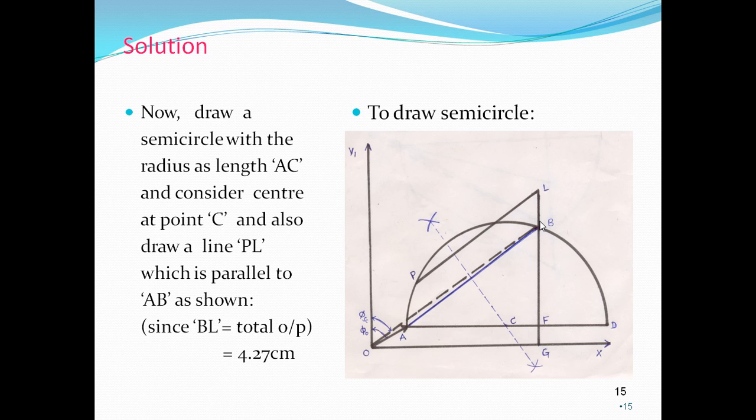So ISN is equal to ISC into V1 by VS. And cos phi S is equal to WS by VS by IS. So ISN is the short circuit current corresponding to normal voltage. With the same scale, the vector OB represents ISN at an angle of phi S with the vertical axis.